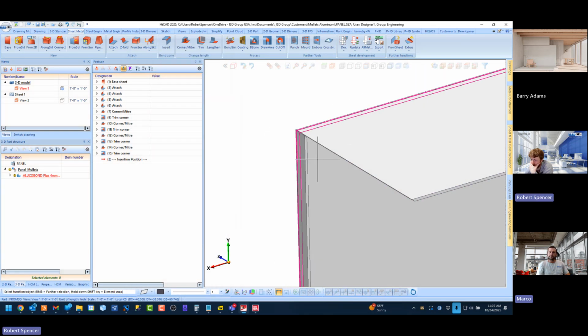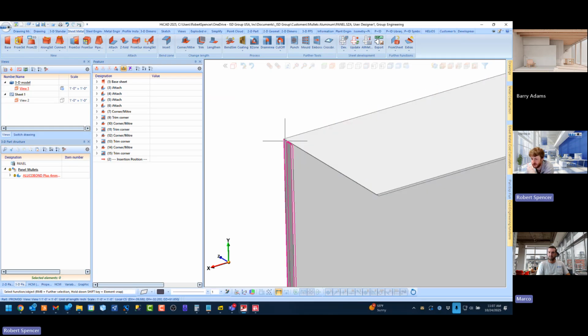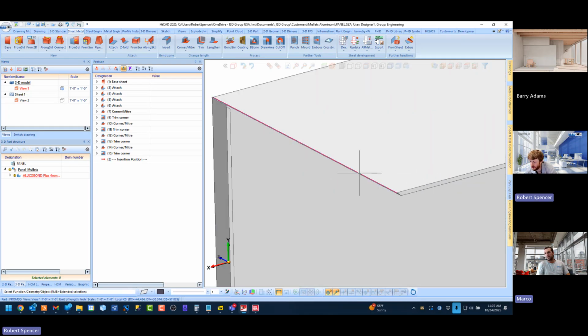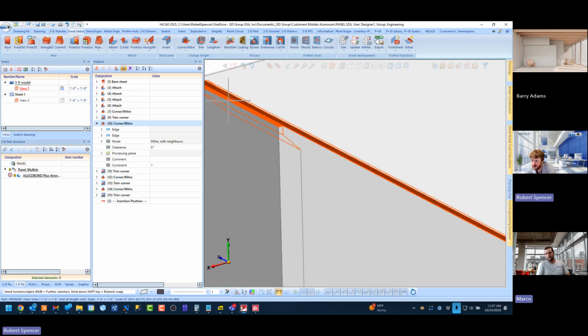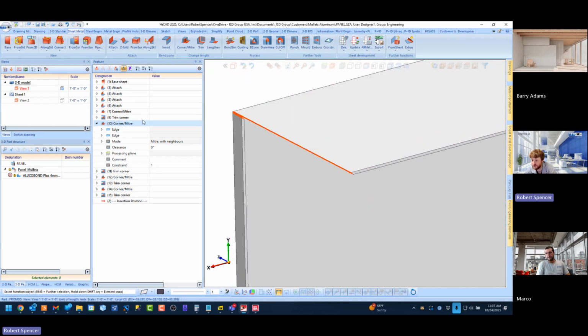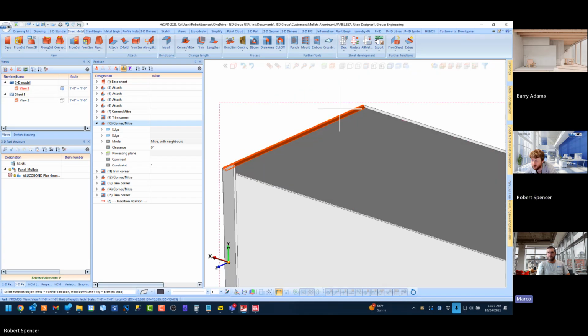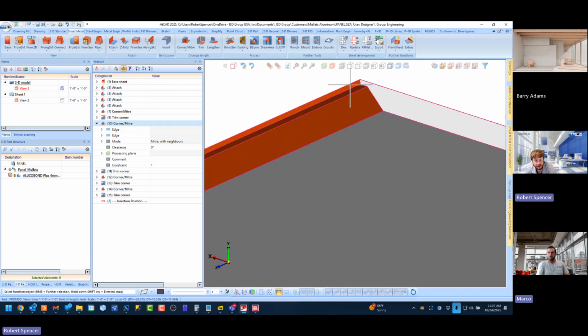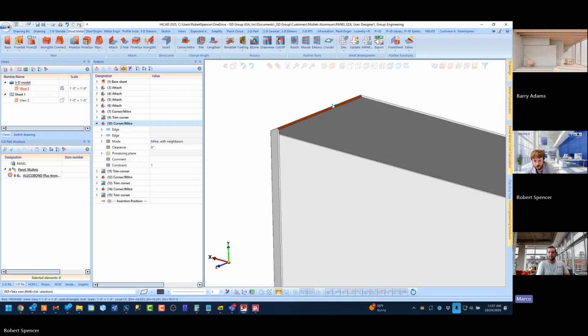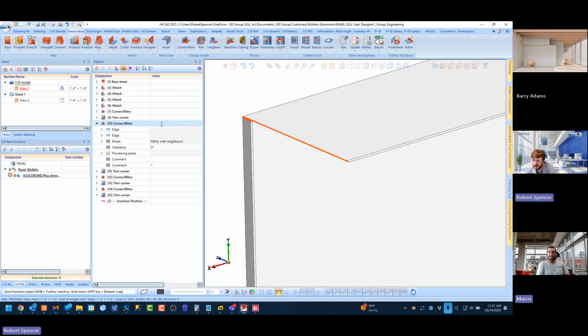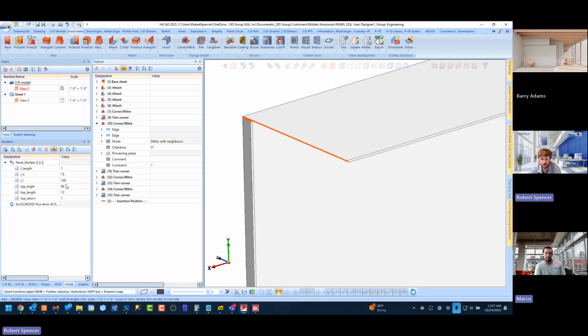Oh, okay. I'll have to show Barry when he gets back. So what I sometimes have to do is this groove, this miter, sometimes screws me up when adding flanges. So technically this miter is used for a standard situation. Remember when we don't have a connection top, they created that nice tight corner here when our top return is off. So when the flange length is 1 or whatever we have set here.